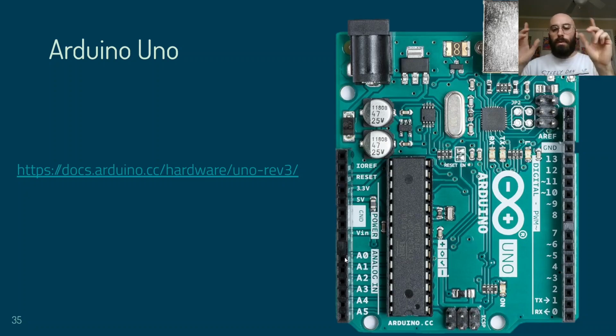By using these different pins and connecting them up to circuits, we're going to be able to do an almost infinite number of things. There are so many different possibilities. But I guess the key distinction we want to make is digital versus analog. Digital has 2 states, on and off, either 5 volts or 0 volts. And then analog has a whole range of different values between 0 and 5 volts. With digital, we can use the pin as an output to drive out a voltage, or as an input to read in a voltage. But the analog pins, we can only read in voltages from. So that's basically everything this can do.